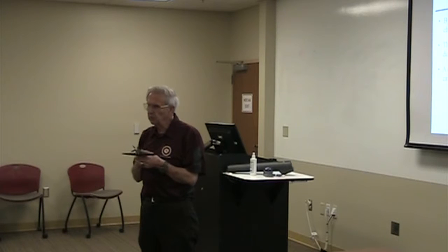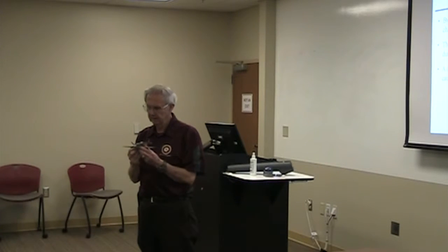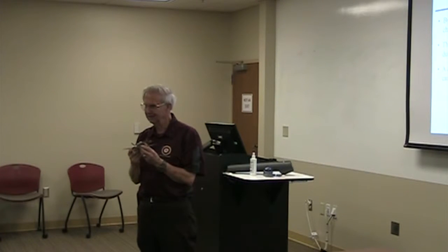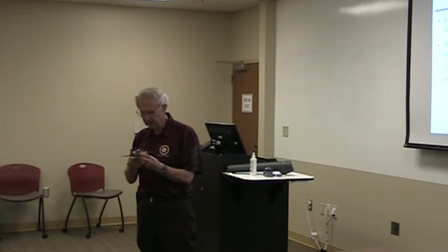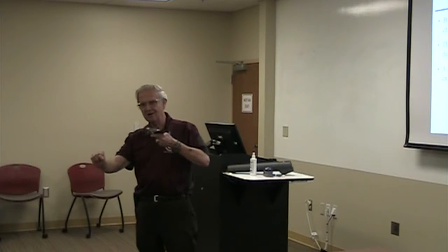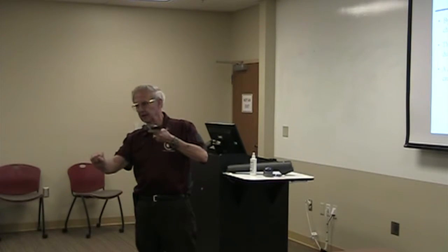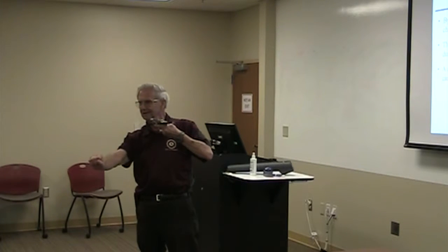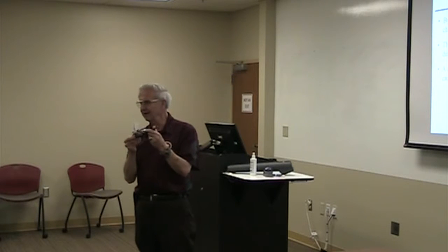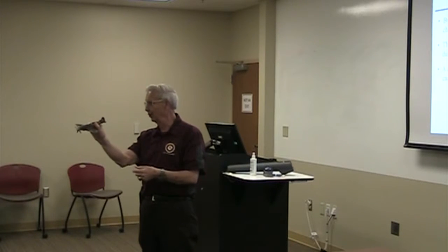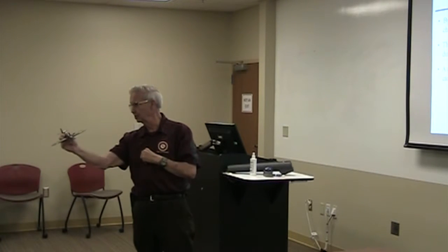One of the things we worry about in the flight test business is a thing called rudder lock. And we'll talk more about that in a bit. But what happens is the rudder, as you get higher and higher side slip with the rudder, next thing you know, it goes zoom, and there it stays. And here you are in this horrendous side slip, and of course the airplane doesn't have much drag going this way. It has a lot of drag going this way.